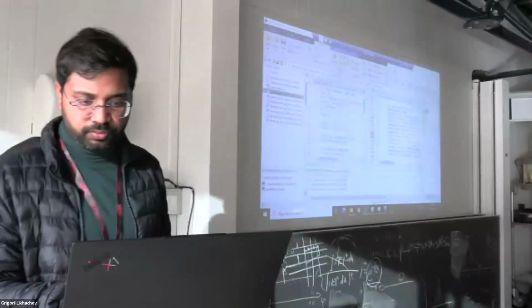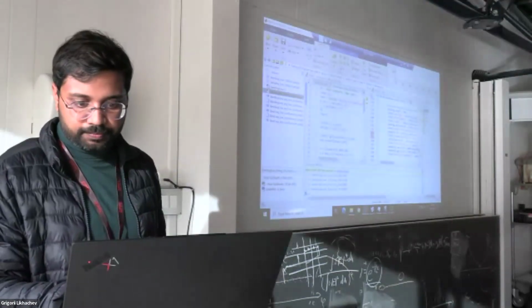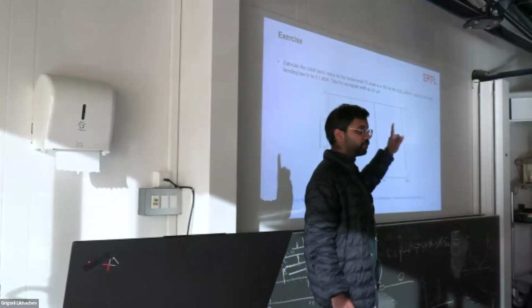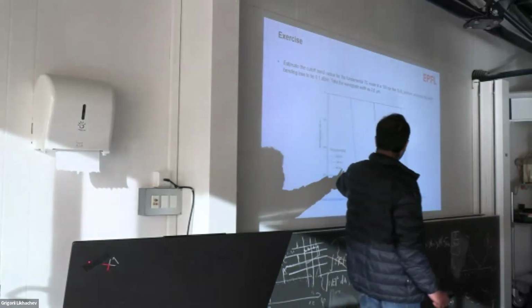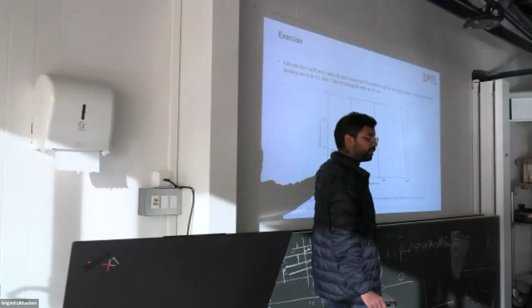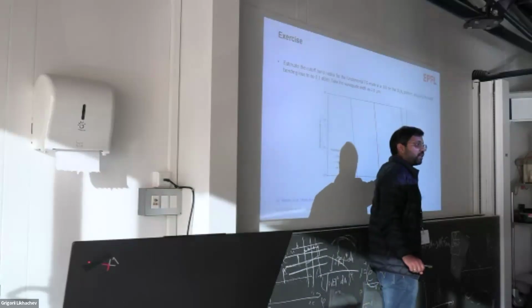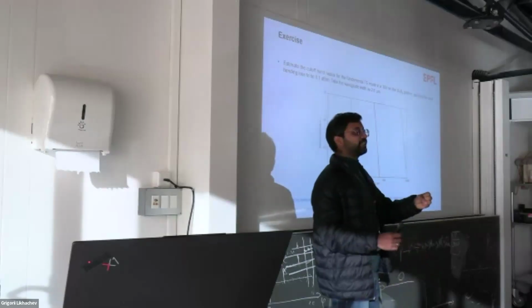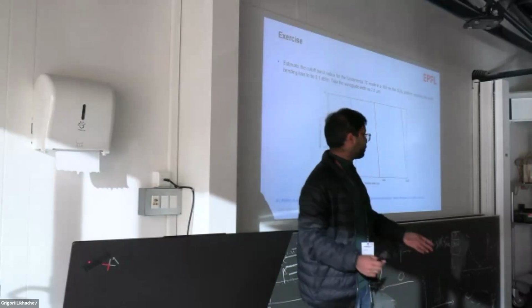So I just go back to the presentation quickly, just to conclude faster. Yeah, so if you see, this is the SI of the Hertz line width paper, the Nature Photonics paper from the group of Don Bowers. These are the plots they have made for 200 nanometer, 250 nanometer in their case, and 100 nanometer. And they show that if you make it thinner, there are very high bending losses, even for big radii. So as we go thicker and thicker, we can make tighter and tighter radii. So that's what they show.